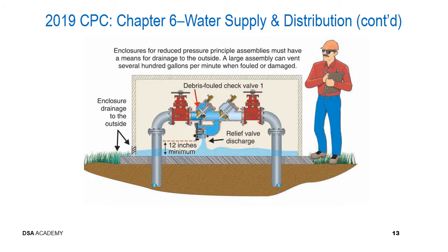This picture is simply an illustration which drives home the point that there are some situations where one of the larger backflow prevention devices, similar to what we discussed before, a Febco 856 or something of that nature, is commonly used on water supply systems to buildings. If they're located in a vault, it's extremely important that the designers know first that in the case of these things failing, a tremendous amount of water can be discharged in a very short amount of time.